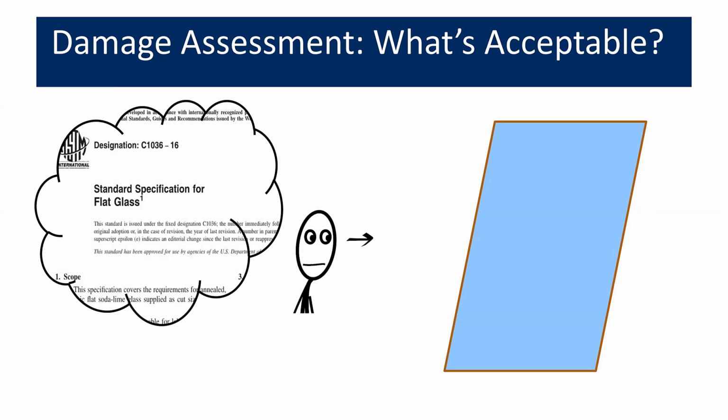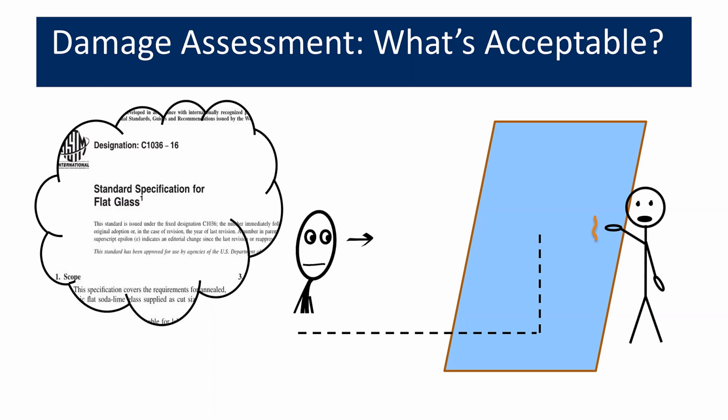The premise of this standard is you begin observing the glass from a prescribed viewing distance, starting from the furthest viewing distance from the glass and moving progressively closer, so that the viewer is not biased. We believe there should be another assistant at the glass marking whatever blemishes the observer sees and determining whether it's a blemish or maybe it's just some benign surface debris that can easily be wiped off the glass.